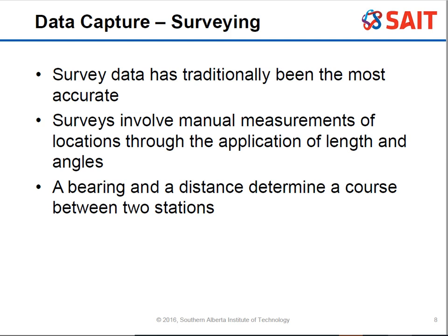There's something called a bearing. This is an angle where you can set an arbitrary 0, and then you can create an angle based on that arbitrary 0, or you can set it based on an azimuth. So a bearing is between 0 and 90 degrees. It's not necessarily anything past that if you use a quadrant bearing. There's other bearings which are allowed to be greater than that as long as it's within 360 degrees.